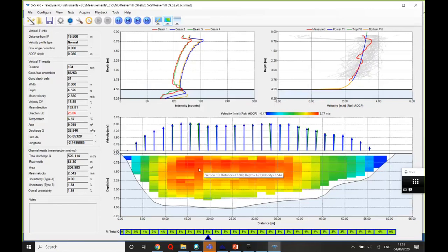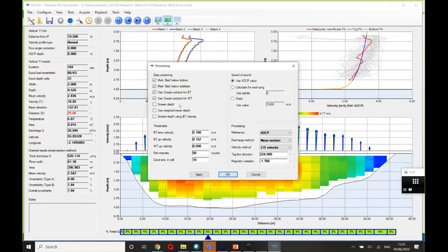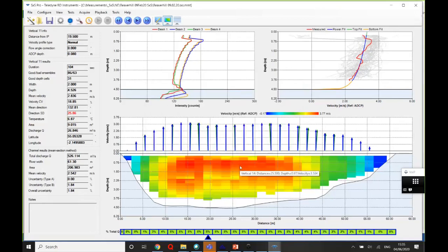So, like doing a current meter gauge and taking regular stages, and then somehow in WISKI later you're going to have to apply a mean stage to your gauging because it's taken so long. We normally just use the average from the start to the end and put that in. Yeah, that's it. In our stationary software, you can, for every vertical, put in a gauge height, and it will link that to the time, and it will weight the rise and fall over time.